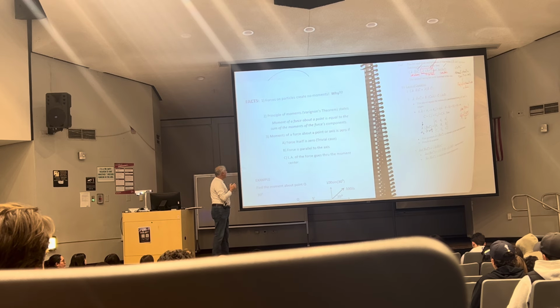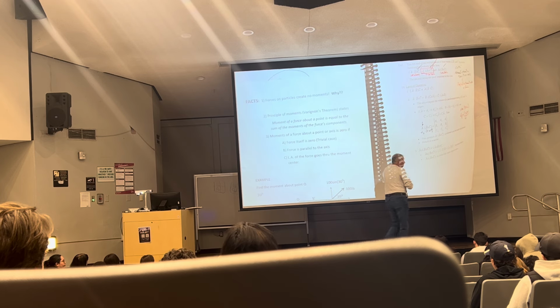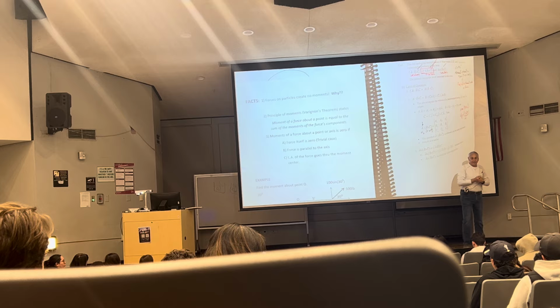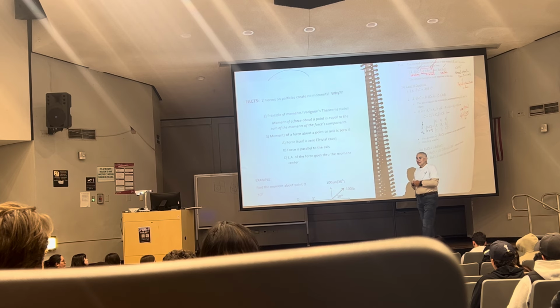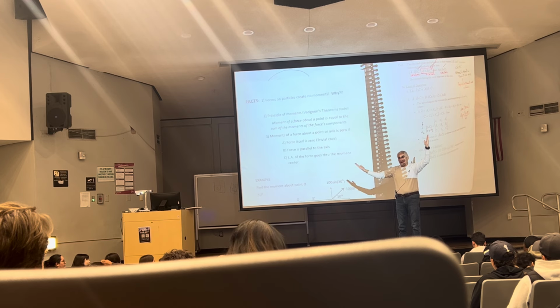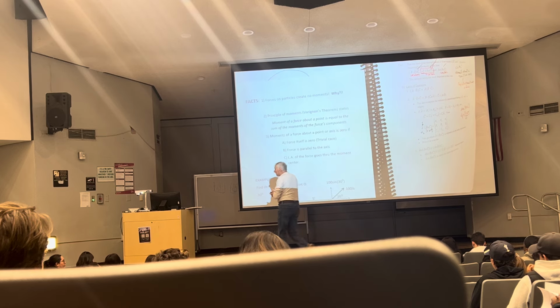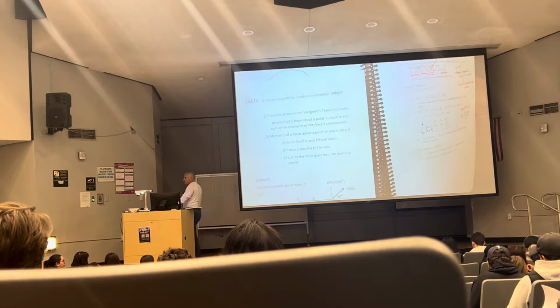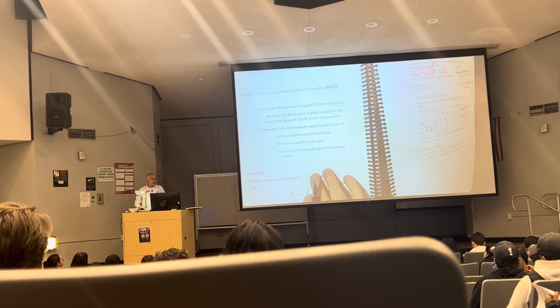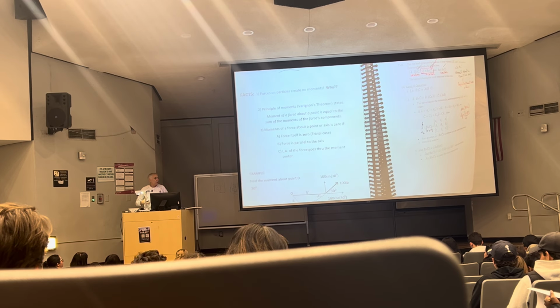All right, number 2, principle of moments. One of our 12 concepts in this lab, also known as Varignon's theorem. Varignon said, it doesn't matter whether you take the force or you take the components of the force, the x and y components, and find the moments using the components. If it's easier, go ahead and do it. You get the same result. Sometimes you have to do more work to find the perpendicular distance. You don't have to by Varignon's theorem. Just break the force into its components, use the components to find the moment.